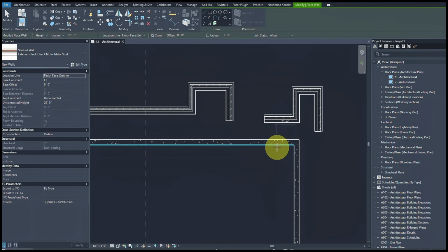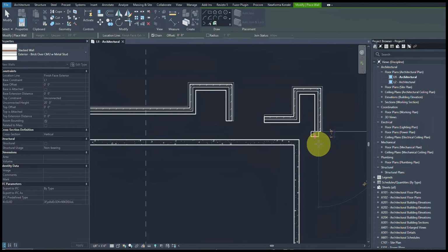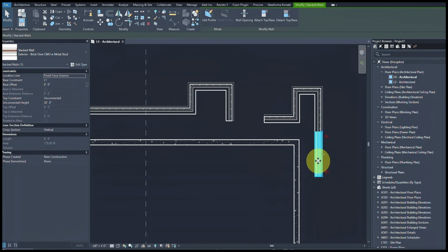But if I want to change the thickness of this and bring it inside, that's what this one helps with. So basically this is going to give me that ability to just be outside. You can see the line right here. So let me just do it directly from where it is. Right now, this line is basically on the exterior of the wall. So if I select this wall and add the thickness, the wall is not going to grow outside, it's going to grow inside, right?